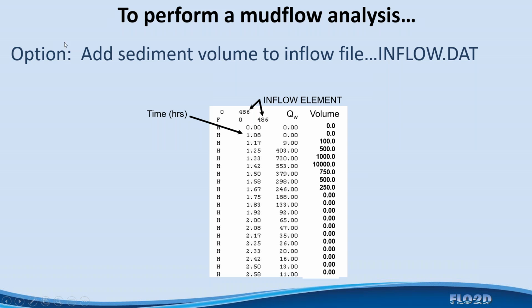Now, another way to perform this, and we'll talk about this more next week, is to add the sediment volume directly to the inflow.data file. So you would need to go out in the field, look at the conditions, look at how the sediment's arriving to the water course. It may be through landslides, through erosion of the channel bed and banks, scour to bedrock, overland sediment yield and sheet flow, whatever the sediment loading physical process is. If you could identify that and estimate it, then you could add the volume directly into the inflow.data simply by putting in a number greater than 1.